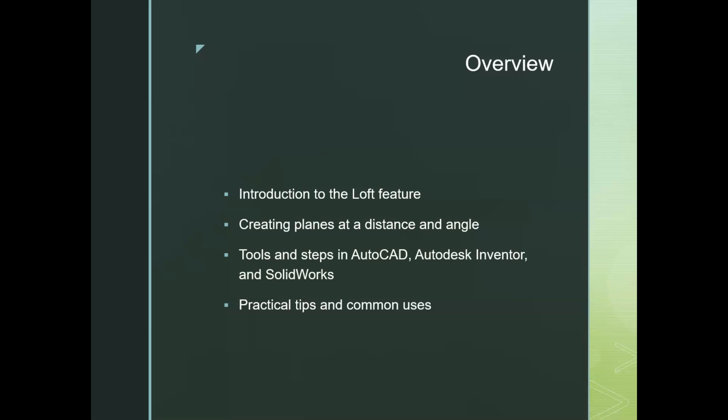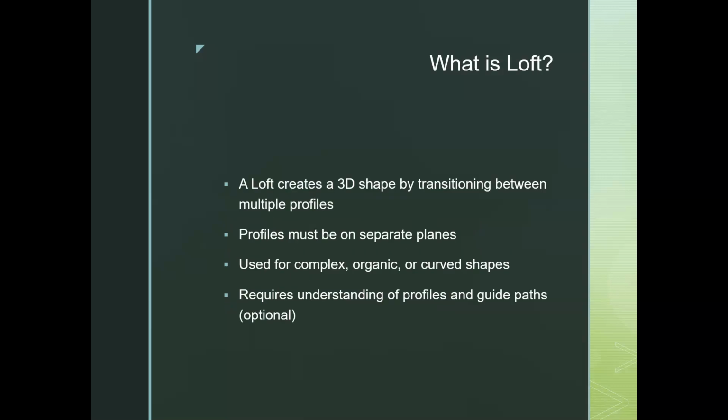Okay, so what we want to discuss first is what's a Loft command, right? This is one where we're going to create a three-dimensional shape. Now, the one thing I want you to remember here is that it's going to be multiple profiles, right? So we have to create multiple profiles. Everything we've done so far is on one profile. Those profiles have to be on different planes. I know I'm repeating myself constantly, but that's the way your mind has to think of it. So I have to create these profiles, and they have to be on separate planes or separate elevations.